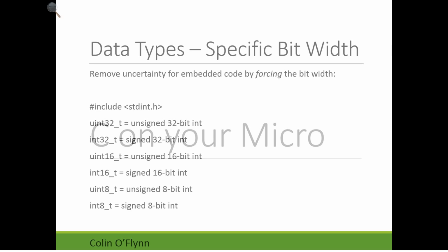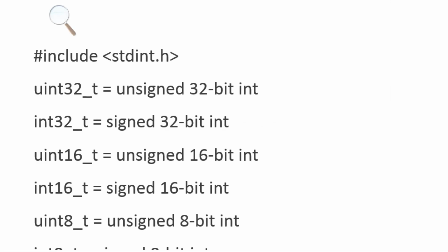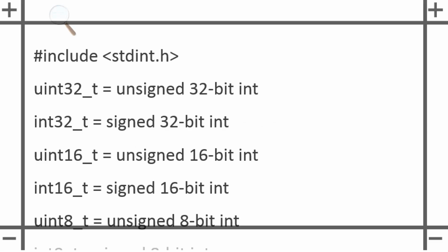I have a question about performance for those. Yep. You said that on an 8-bit processor, the 8-bit data types would be the fastest. On a 16-bit processor, would 8-bit data types be slower? No, basically, you won't lose anything. So typically, it depends a tiny bit. The general answer is no.